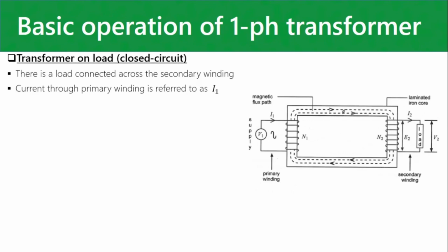All right, when the transformer is on load now, you can see you have a finite current flowing in that secondary circuit. Now your primary current will get bigger as a result of I2 getting bigger. It's not like you inject a current in here and then find a place for the current to go on the secondary.